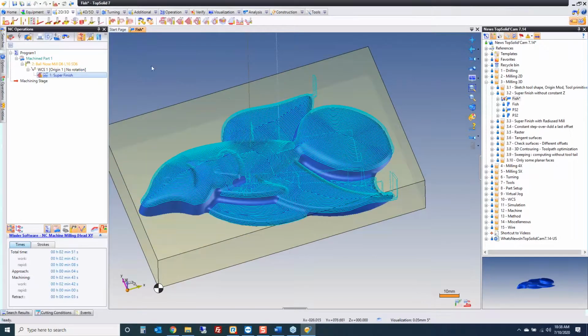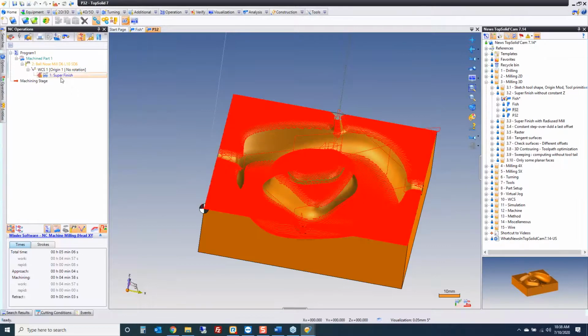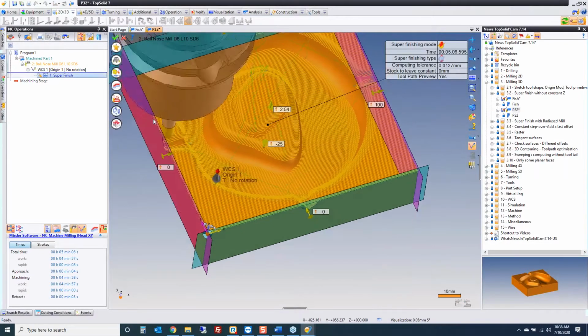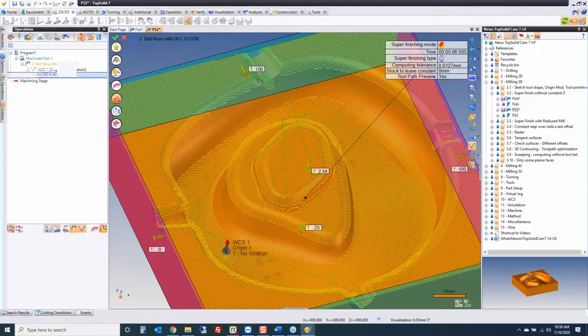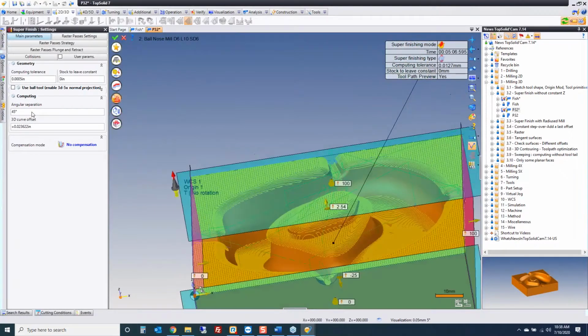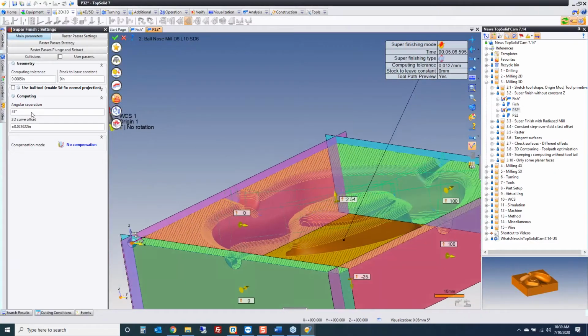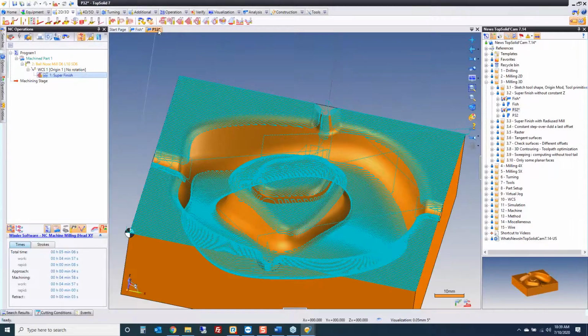Okay. If we go look at another sample really quick here. Again, same concept. This one is just doing a raster pass instead. So I have it set to the raster mode right there. Again, angular separation from 0 to 45 like so. And you can see all the steeps are being ignored, and this is just hitting on all the shallows. So small improvement, but kind of cool.